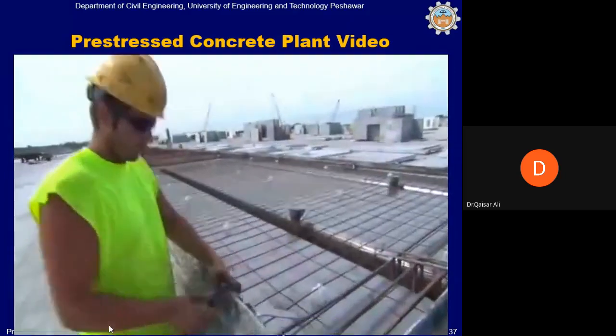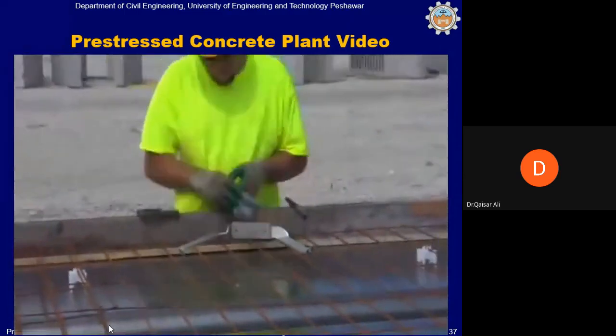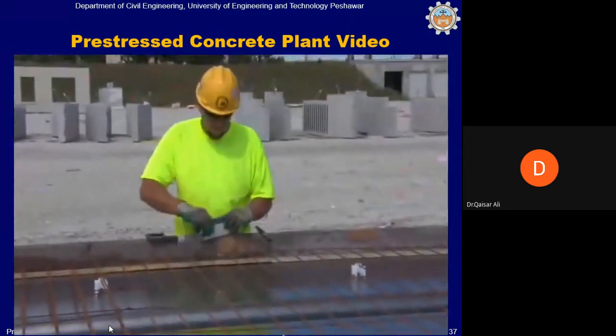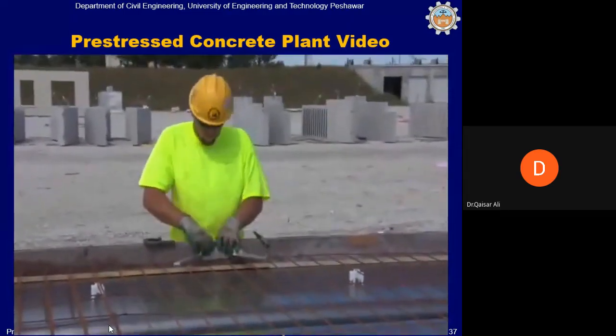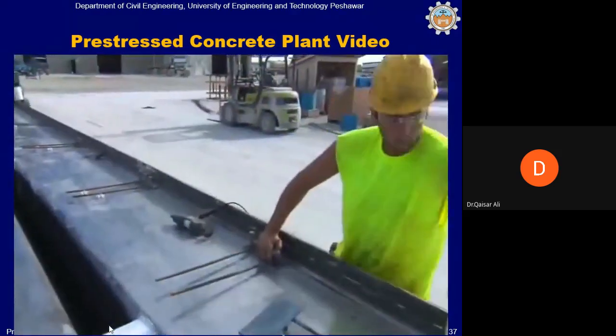along the edges. In this case, one of the double T's in the bed has typical flange connectors applied along one edge and special flat plate connectors applied along the other edge to accommodate connections across an expansion joint.